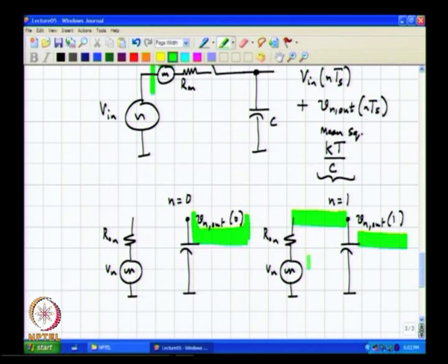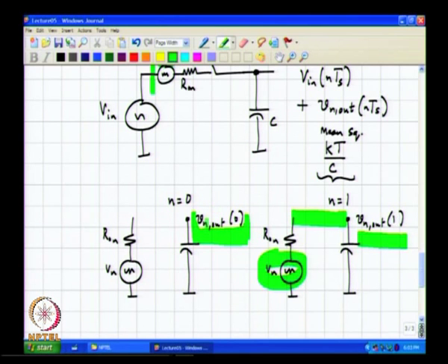It is basically like having an initial charge on the capacitor that is being driven by a noise source. And as he pointed out, between 0 and T, the waveform Vn of t is completely uncorrelated and independent of what happened in the previous clock cycle. But what happens to Vn out of 0, which was stuck on the capacitor when you began? It might, or will, depend on R on, correct? Can it charge or discharge?